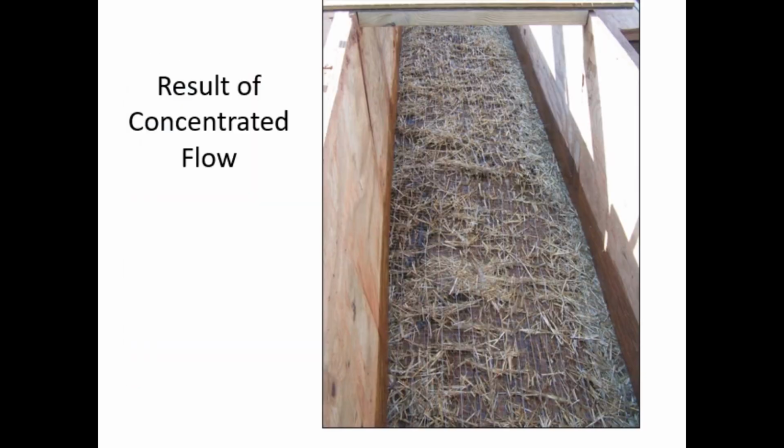The tractive shear forces caused by the flowing water can have significant effect on the protective fibers in the RECP. When the anchorage or the RECP construction is insufficient, the soil surface may become exposed directly to the flows, accelerating the erosion process.